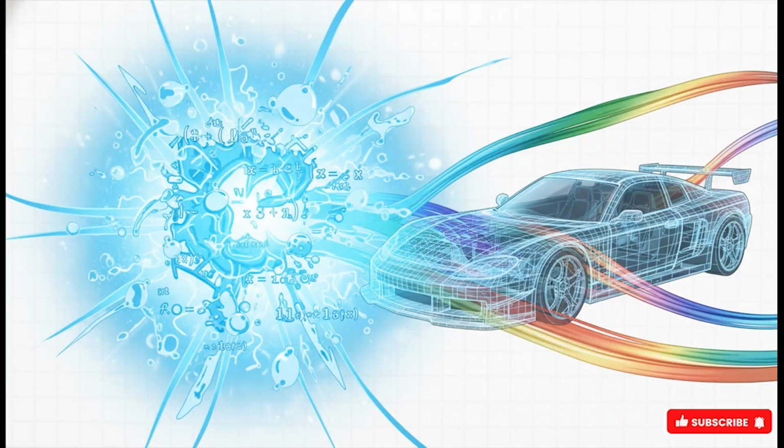Now here's the crucial part. CFD isn't just making educated guesses. It is crunching the numbers on the fundamental laws of physics that govern the real world. We're talking about equations like the Navier-Stokes equations, which are basically the fluid version of F equals ma. By applying these hardcore physics laws to that digital mesh, the computer spits out this massive set of numbers that is, essentially, a snapshot of how the fluid is behaving.